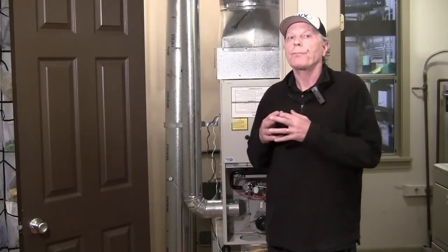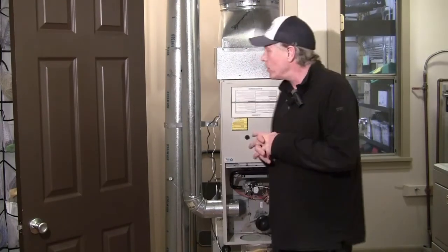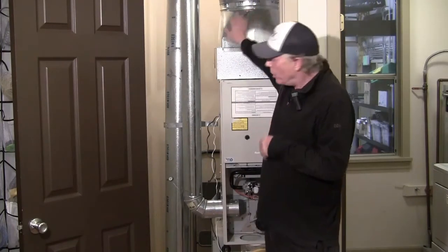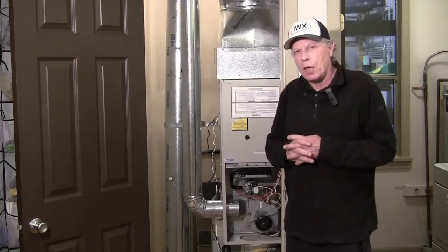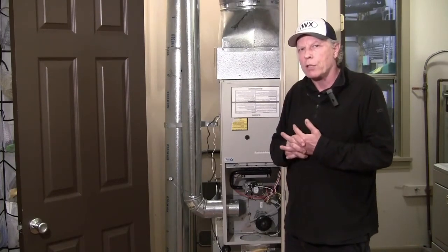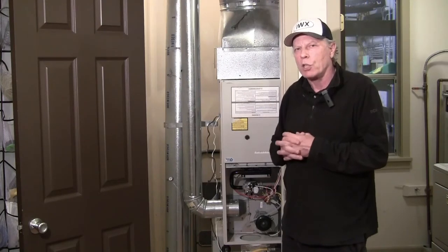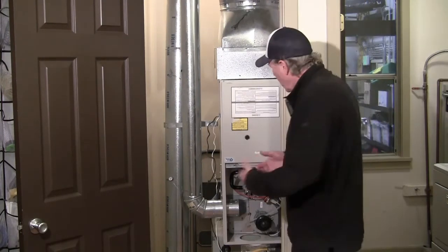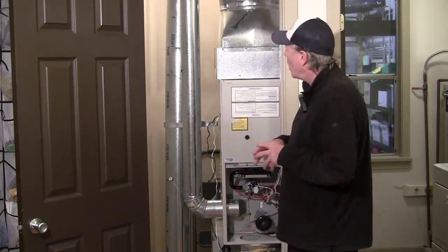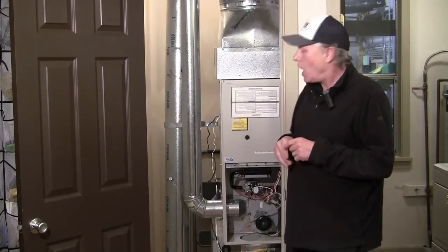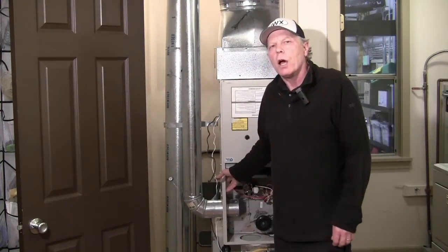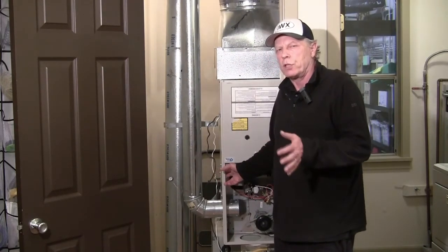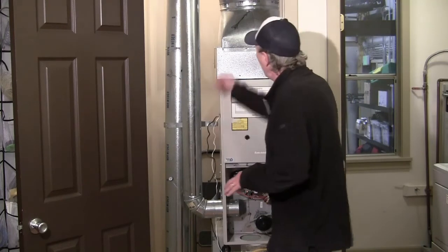On line 6, the candidate's required to measure heat rise on the furnace. I have a thermometer up here in the return and one here in a supply duct going to the upstairs, and I'm going to take a look at those. The reason we measure heat rise is we want to make sure that we don't have any blockage in the ductwork or we're firing at the right rate, and heat rise is a good diagnosis of that. I find what the standard for heat rise is always on your data plate here. I looked earlier here and it's a 35 to 65 degree temperature differential that we're looking for.